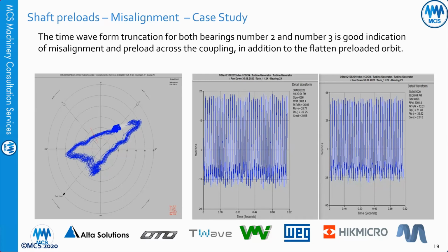Perfect. Thank you. Can you explain about the acceptable region that you were showing, I believe, in the last case study? What is the acceptable region? Okay, for any machine, especially turbo machines, I normally use two standards: 2816, which is for absolute casing vibration level, and 7919. If I have a good memory, 7919 is for the relative displacement.